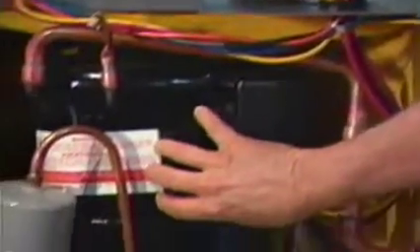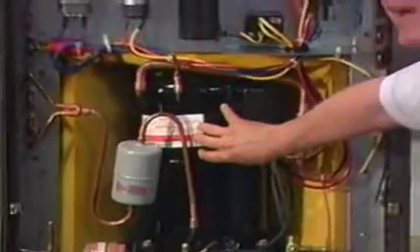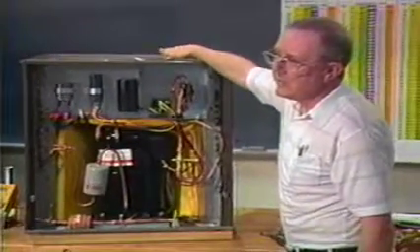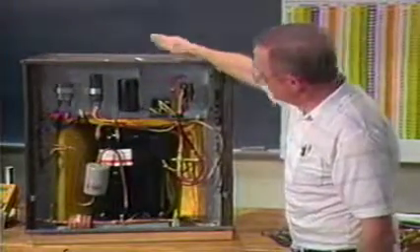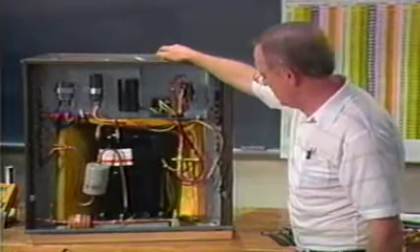This load here is the compressor. It actually is the major load device in this unit. Also, we have another load up here, which is the fan motor, the condenser fan motor. These are the 2 power-consuming devices, or the load, in this unit. Every system will divide itself up into circuits and sub-circuits that will consist of a power supply, through the path or through the conductors, to a load. The load is also known as the measurable resistance.